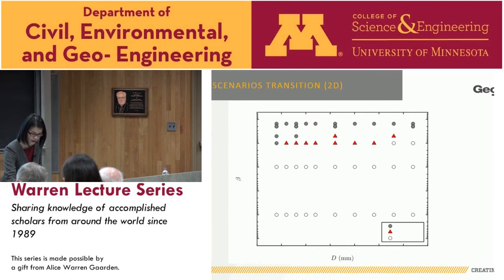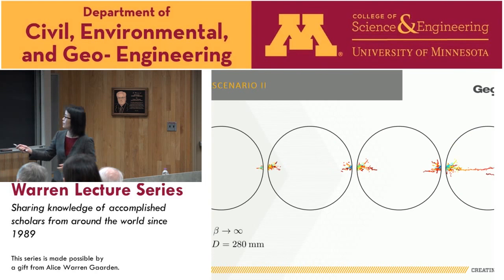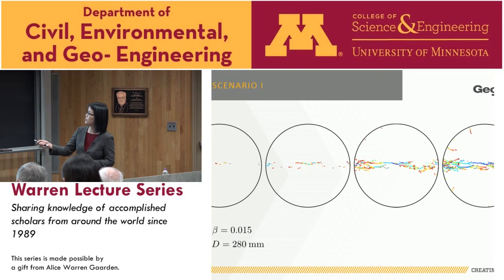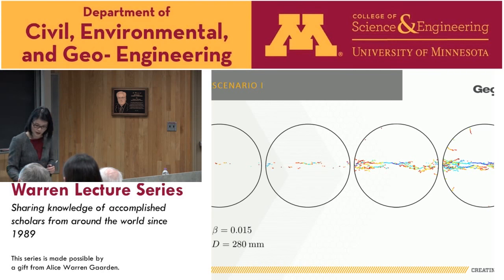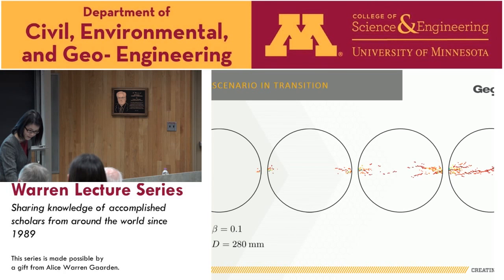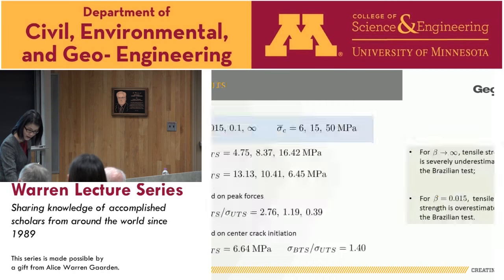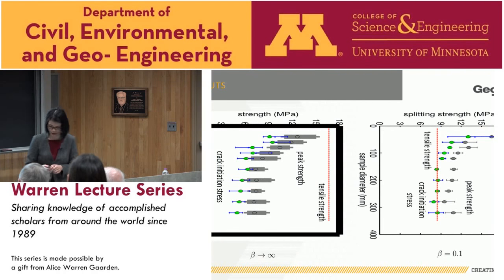But you have progressed from initiation, and you still have to progress that far to get to the peak of the force displacement curve. So the tensile strength, if you are determining it from the peak force of the force displacement curve, you are actually overestimating it. So I will just show you a summary.